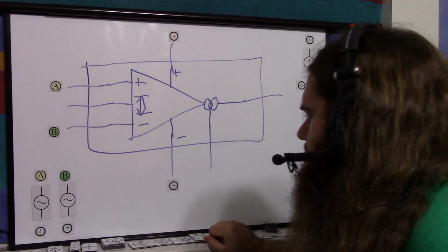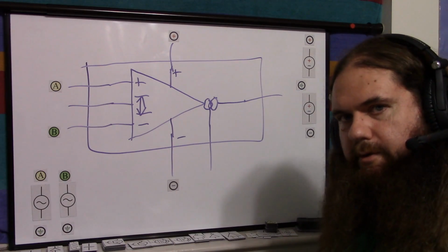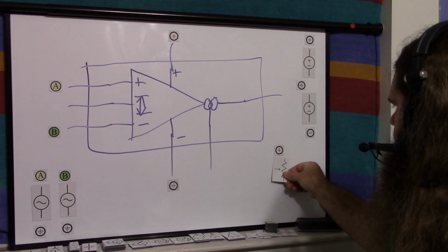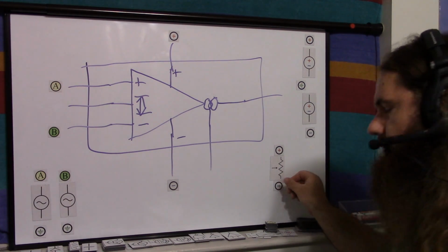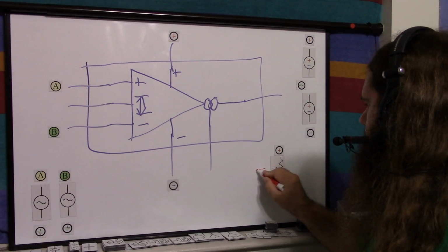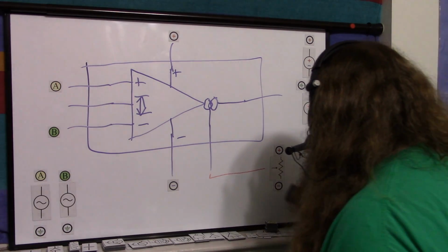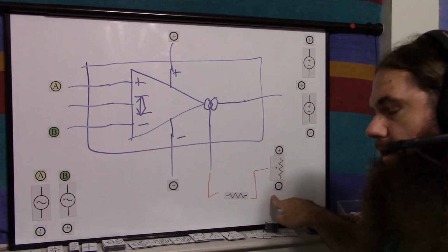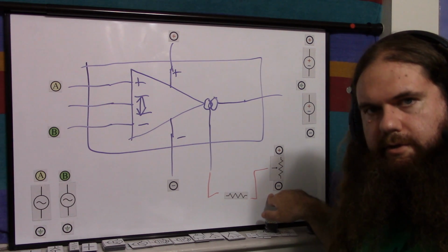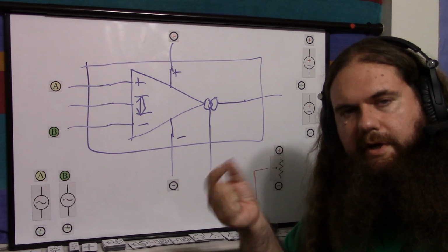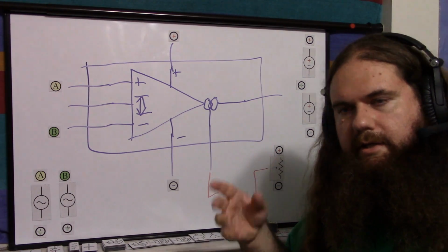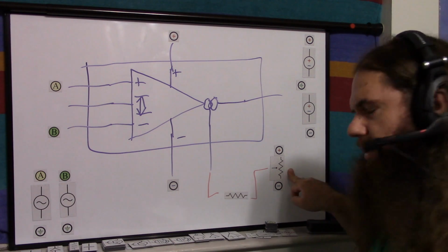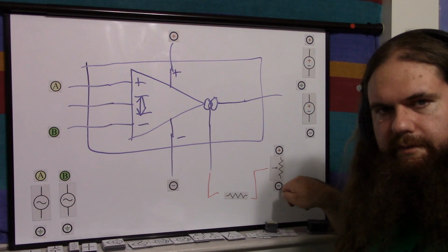your gain control. So very simply, let's say you have a physical knob. If you have positive into a potentiometer and negative, not ground, negative, then here the wiper would be your input, but I forgot the resistor. So a voltage divider through a resistor into here. If you're using a microcontroller or whatever, some sort of varying voltage programmatically, then instead of this potentiometer, you just put the voltage through the resistor. But if you're using a physical knob, you'd use a voltage divider like this.